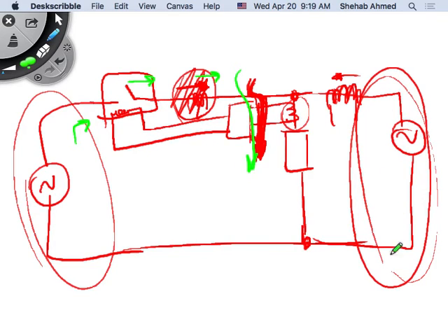I'm assuming I don't have a PV system yet. If I don't have a PV system, then the fault current will flow from the source into the fault here. Right? So in this case, if I have my CT over here, is this CT going to see a high current? It will not. So we originally said that this is a good place to put the CT. But now I'm saying if the fault happens here, this is not a good place to put the CT.